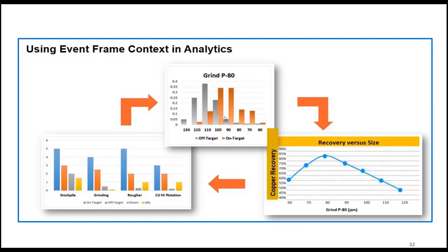So the next step is that I'm going to focus here on a case that we have been working on where you want to optimize your yield, the recovery in this case of the metal, in this case copper, and that one has a certain shape. So we know that when we are optimizing, we're always looking for an optimum, but you need to find the right size, which sometimes is unmeasured, so you have to generate that with the soft sensor.